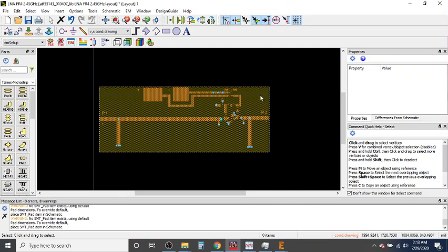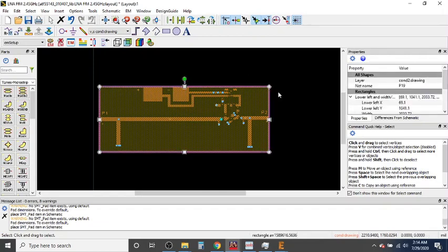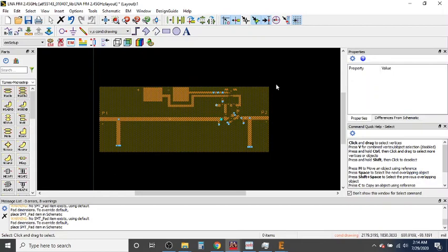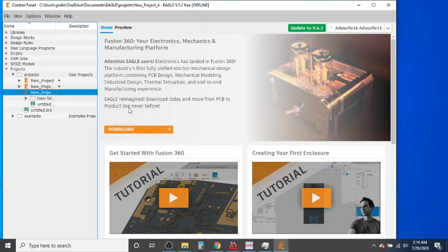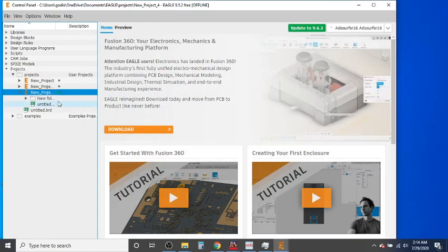If some things are off, they like to make sure everything is correct, the same as every design for everyone else. You want to make sure that they get what they want. So we need to make an outline layer and create the drill files for them.